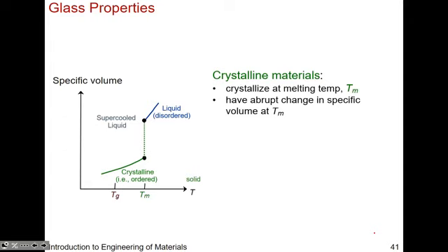You go from some volume, where your atoms are just flowing about. And then let's say you have this instantaneous, precipitous crystallization or solidification. Your volume drops because now all the atoms are close together. They're packed in whatever crystal structure that we have. Okay. In glasses, it's a little bit different than that.